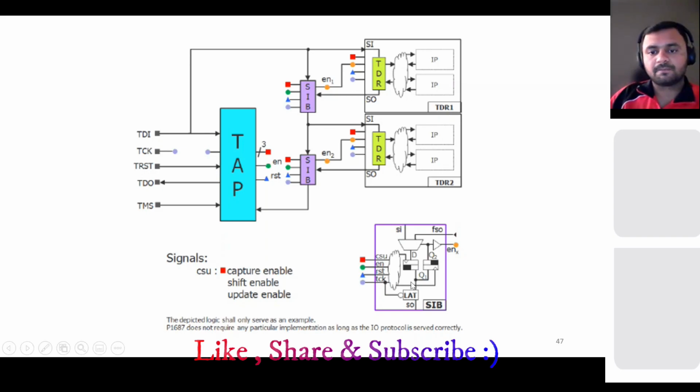This is the more detailed diagram. You have these TAP signals here, and a TAP will generate this, and you have these SIBs, segment insertion bits. You can think of them like a mux. Out of the many blocks, it will select a particular block, like these IPs, intellectual property blocks here, and based on that it will select the test data register.